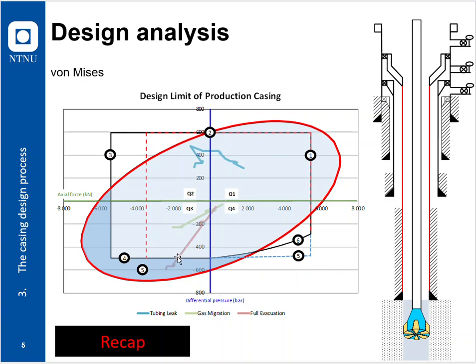And if it happens, is this covered by cement and not very likely to result in a failure? And if you add today the hidden safety factors, maybe that's going to tilt a decision in favor of a weaker casing, or if you know that you're going to sidetrack it and there's going to be casing wear, and that's not considered here, it's going to maybe strengthen your decision in saying, I'm absolutely not using this casing.